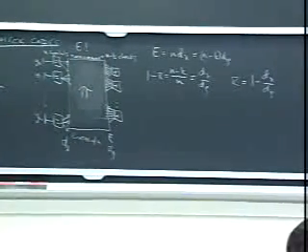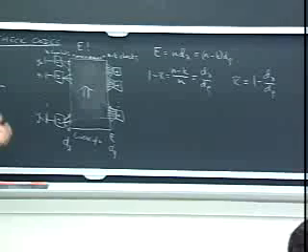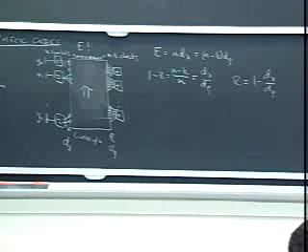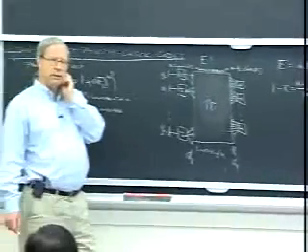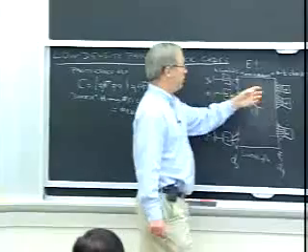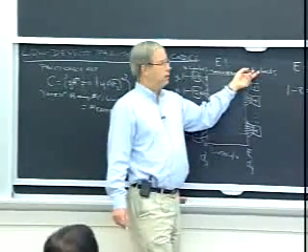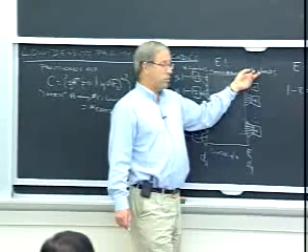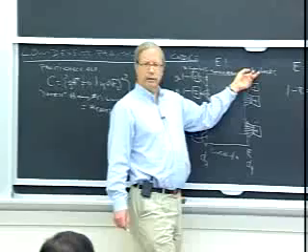It's only nominal rate because what could happen here? I'm basically choosing a random parity check matrix, and there's nothing that ensures that all of the rows of this parity check matrix are going to be independent. So I could have fewer than n minus k independent rows in the matrix, which would actually mean the rate would be higher than my design rate, my nominal rate.